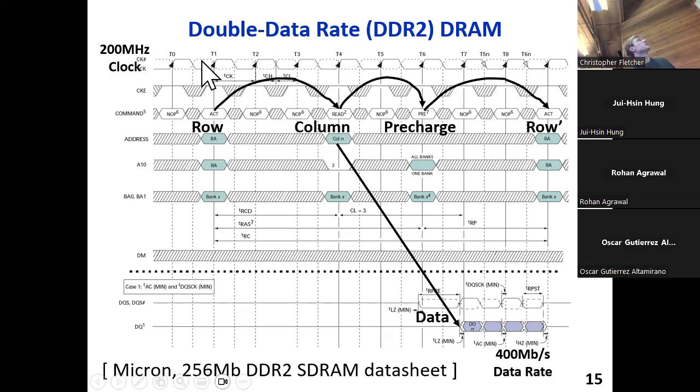Several clock cycles later, where the clock is a clock that you drive at 200 megahertz per the DRAM standard, you send the column address strobe, which is just you place different address bits on the column wires, and then you pre-charge. And going back to what we said earlier, after you do the column address strobe, sometime later, data comes out of this line called DQ, and this is your output data.